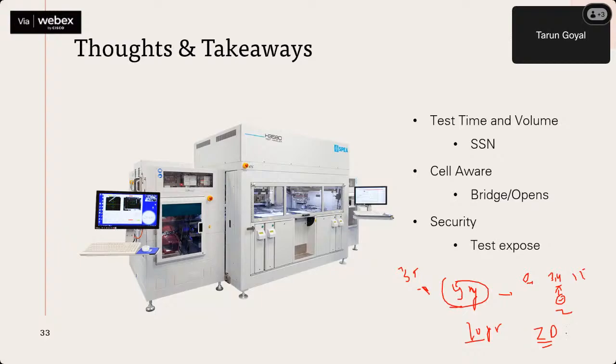So we do a lot of testing, which we call VLV, very low voltage testing. At the transistor threshold level, we test for any manufacturing defect which can potentially become a failure after a couple of years. So we try to activate that kind of defect by creating those environments and tests, to ensure they get detected at manufacturing, because it's the rule of 10, right?